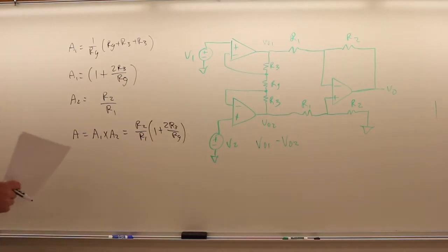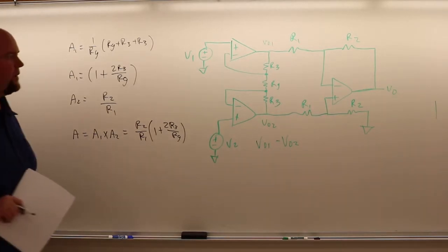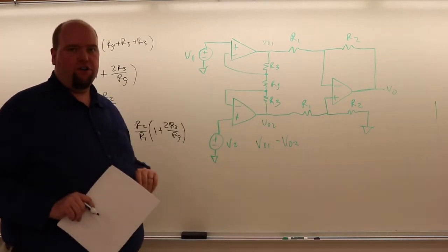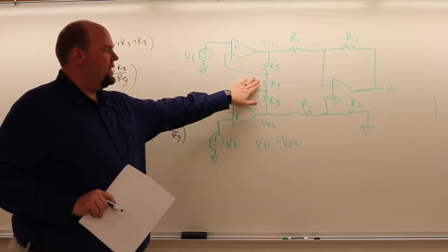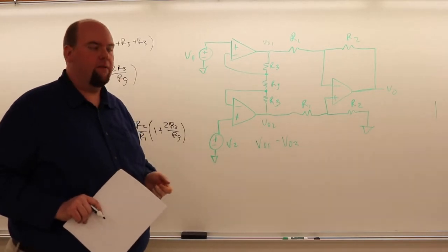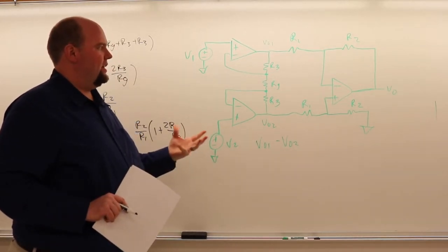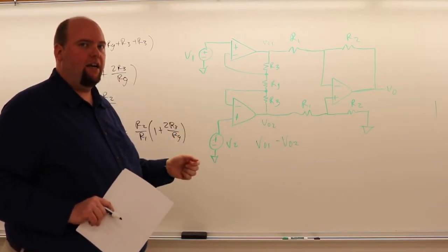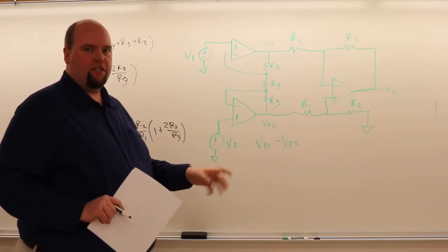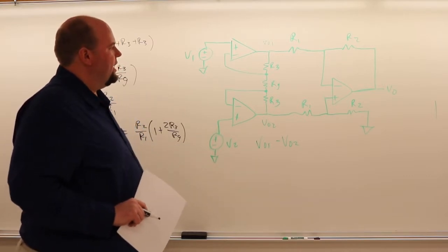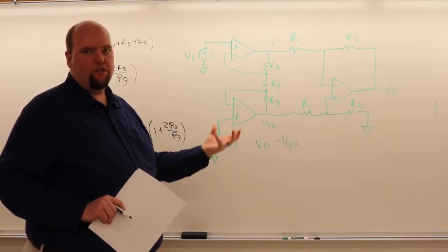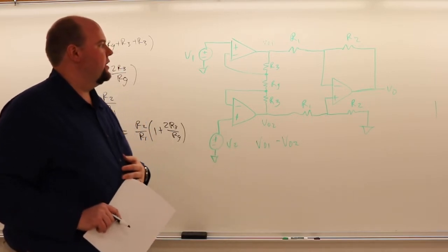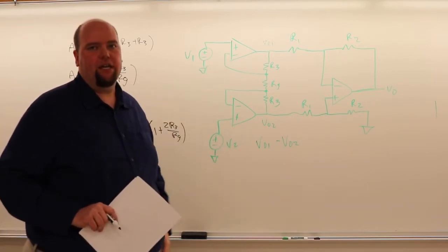So let's talk about changing the value of Rg. We talked in the last video about how you can use a separate value for Rg here. Sometimes you'll have a circuit where there's some resistance built in, and it's designed to have you add a potentiometer. Especially in a system where you want controllable gain, not set by a resistor, but adjustable with a pot or something like that. There might be some built-in gain to allow you to use a standard potentiometer in here. Or you can just slap a standard potentiometer in there as the resistance.